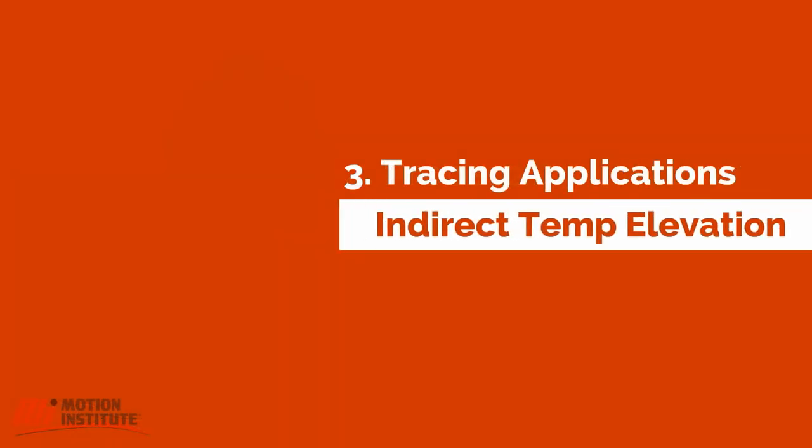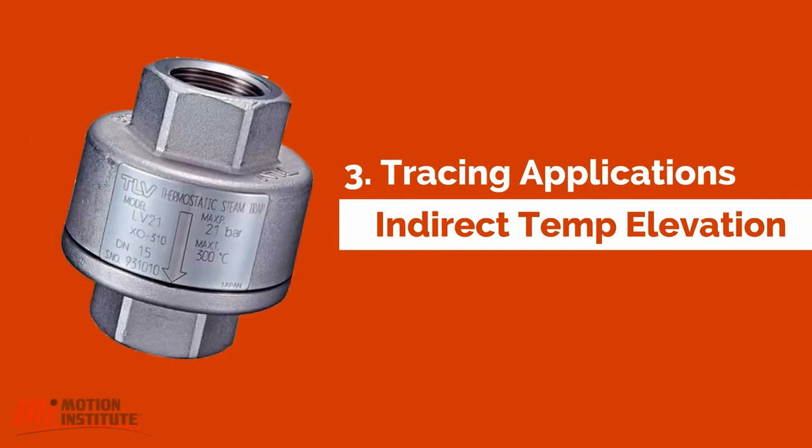Steam tracing refers to using steam to indirectly elevate the temperature of a product using jacketed pipes or tubing filled with steam. Steam traps used in these applications are referred to as tracer traps. The most common trap choice for tracing applications is the thermostatic type.